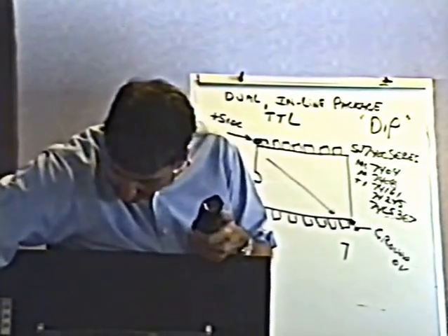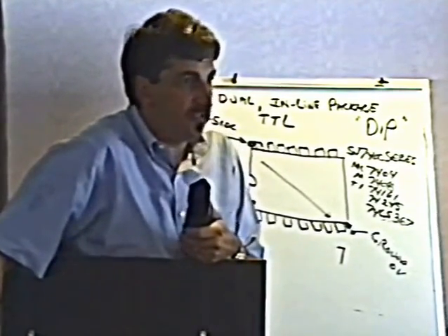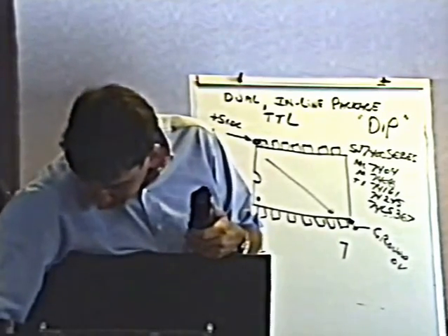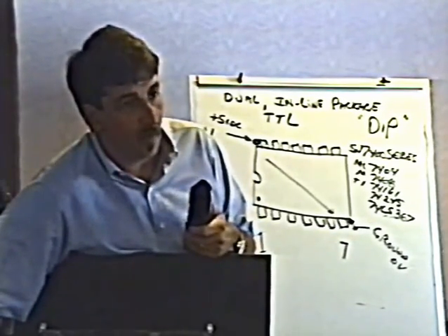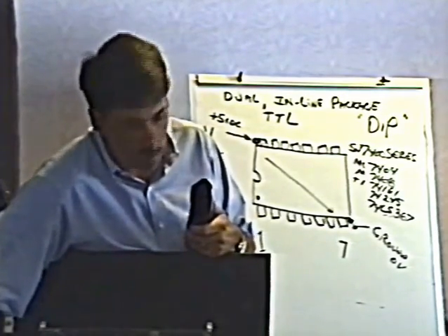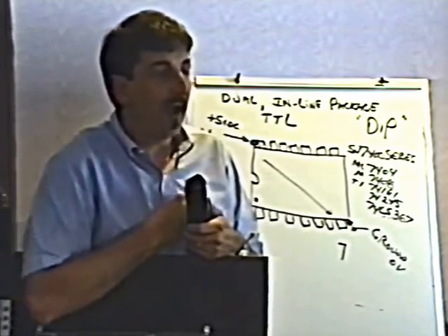We go over here to the connector, 3.7 volts. Not enough, obviously. With the meter connected here on the connector, adjusted up the power supply. I don't know whether someone was messing with it or what, but it was way down too low. Cranked it up to 5.1 volts. Fired right up. Came up.